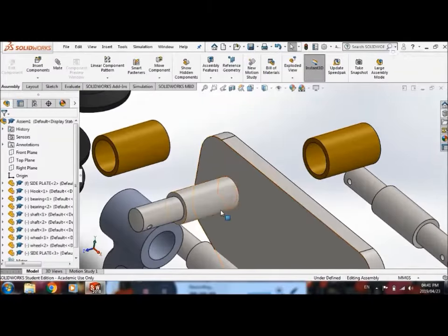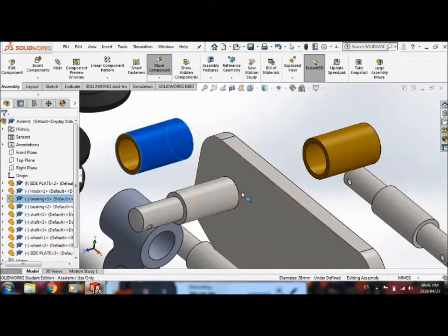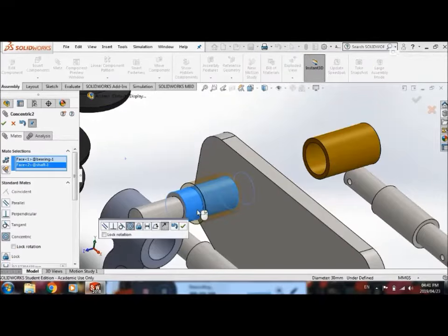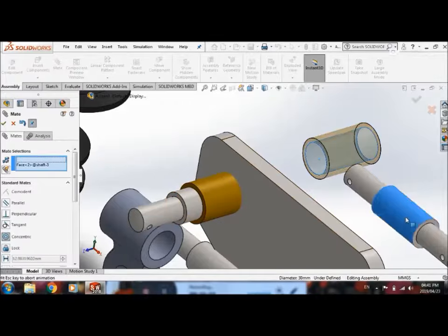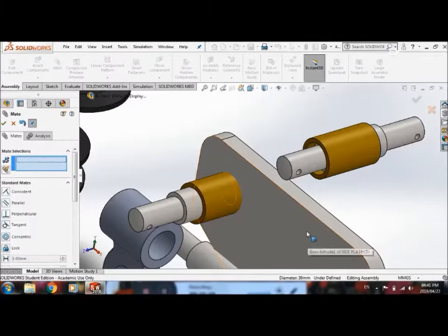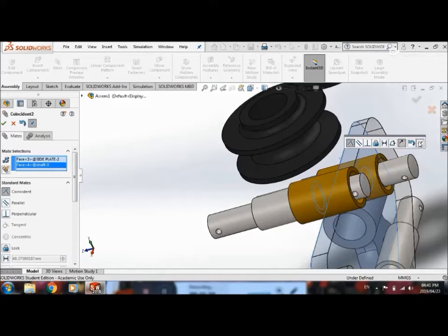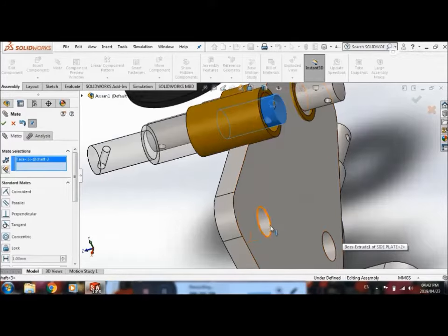So these are quite handy constraints to place on an assembly if you want to, for example, see the movement of when you rotate an engine's output shaft and see how all the internal components move when you rotate it. These constraints basically do just that. So let's put the bearings and the shafts in their places. So I click on mate. This one must be around that one. This one around that one. This one must touch that one. And that one must go through that one.